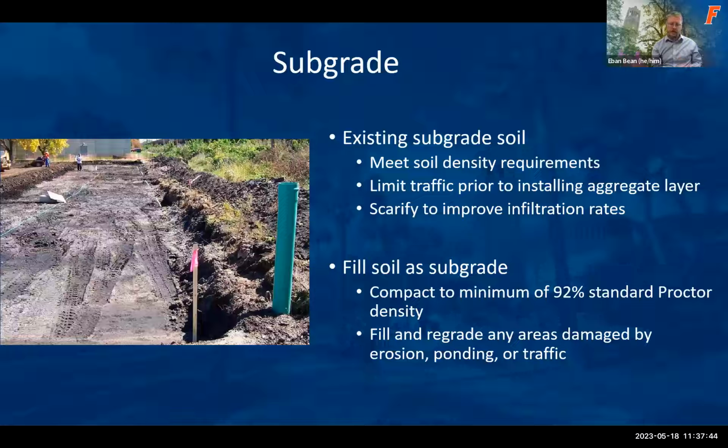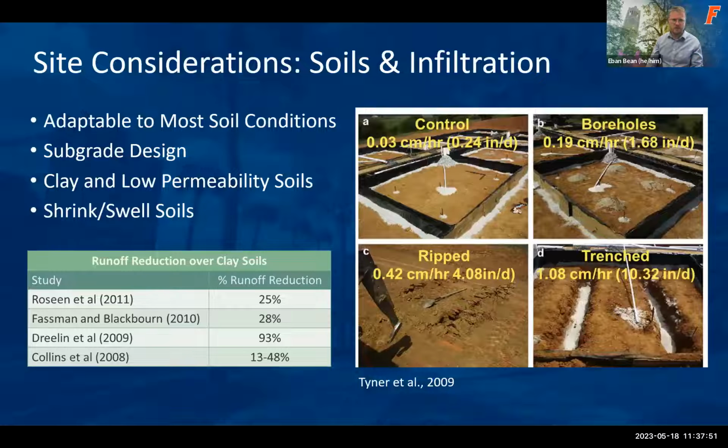You want to fill and regrade any areas that are damaged by erosion, ponding, or traffic. There are some studies that have been done, not as common in Florida, but we do have pockets of clay soils. The research has shown that you can have some pretty effective runoff reduction, even with slow infiltrating clay soils. And there are some ways that we can treat the soil so that we can maximize the infiltration rate of soil that has some clays in it.